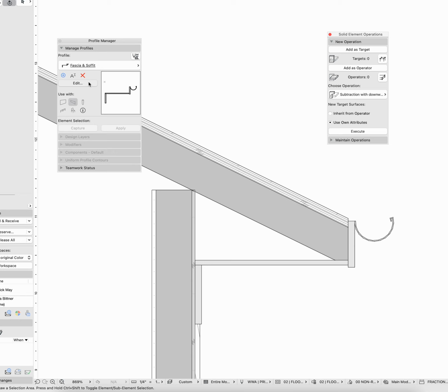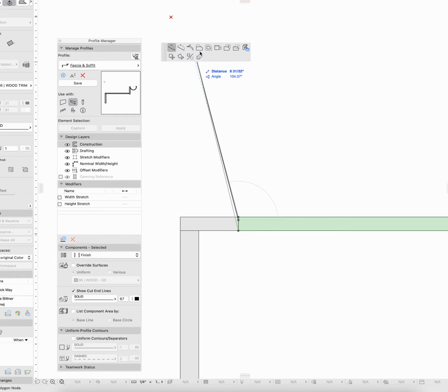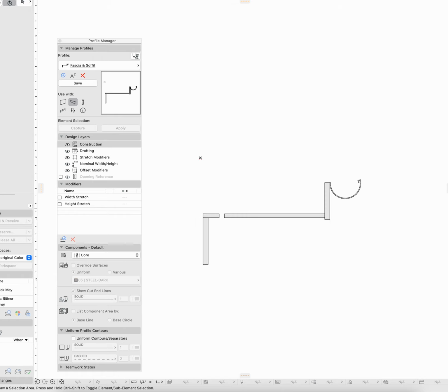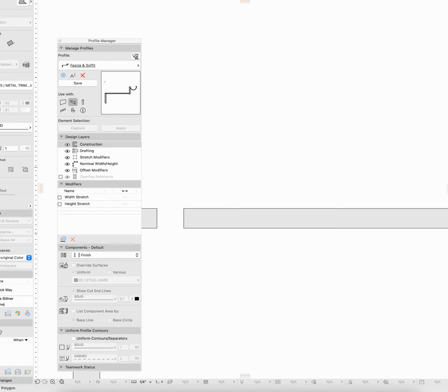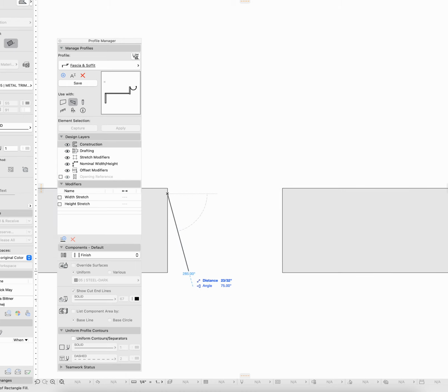The nice thing about these complex profiles is it does give you a global point of control. So let's say that we wanted to show a 1 inch soffit vent here, right? So I'm gonna clip that, I'm gonna pull this over 1 inch. I'm gonna take this building material right here, and we'll just mock in a soffit vent. So there's one,